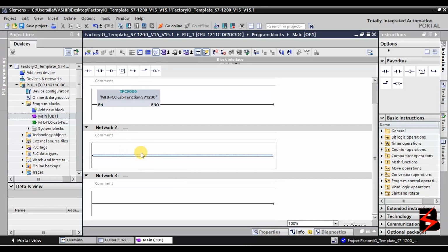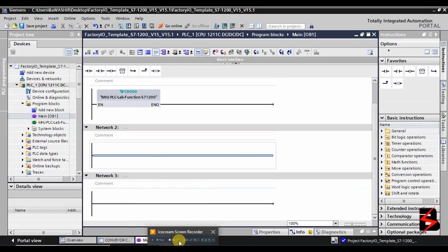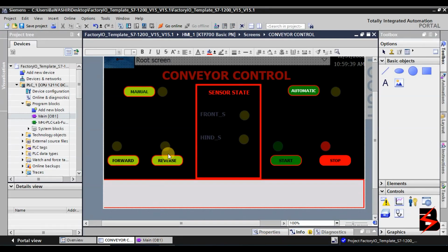And so I'm going to start having here something. Now remember, here in PLC addressing, we have two types of addressing. We have internal tags and the external tags. Internal tags, I mean, those are the memory bits that we use inside the PLC. We don't need to connect physical devices. But external tags are like inputs and outputs, which need to be connected directly to the PLC.